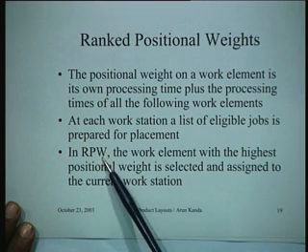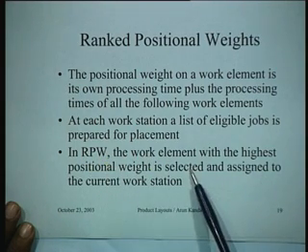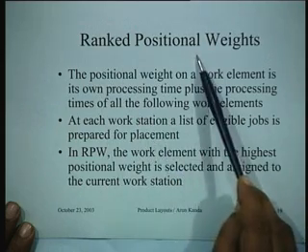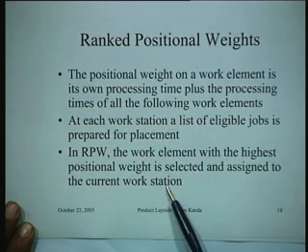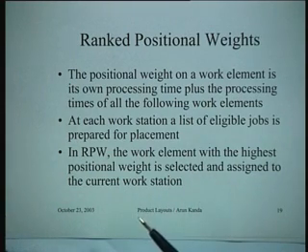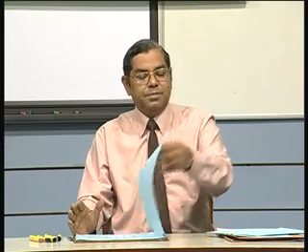And in the ranked positional weight technique, the work element with the highest positional weight is selected. That's why it's called ranked positional weight. It is selected and assigned to the current workstation. So that's the basic logic of the RPW technique. Let us try to apply this technique to the example that we were considering earlier.